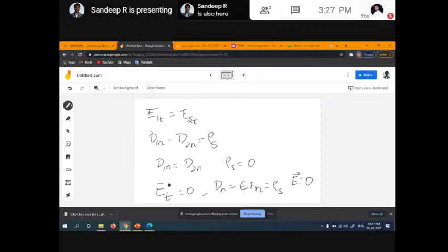Okay, so now we said that if there is a symmetry, then Gauss's law. If there is no symmetry, Coulomb's law. And if it is still complex, try to determine the electrostatic potential, provided it is known at all points. But in a practical scenario, we may not know the potential at all the points. Then we may know it at certain points or at the boundaries. Then how do I determine the V?